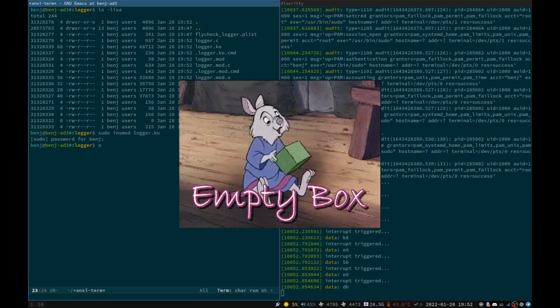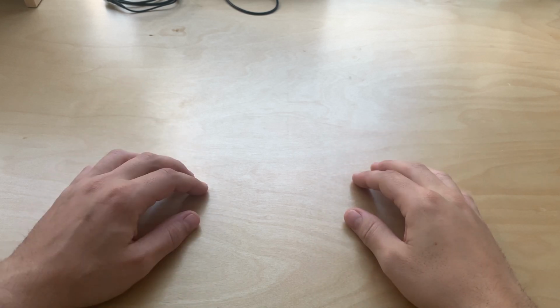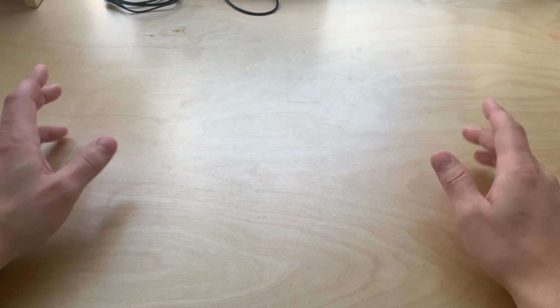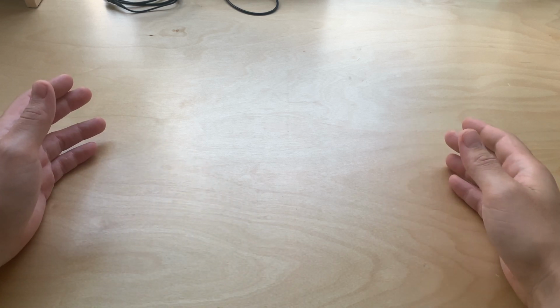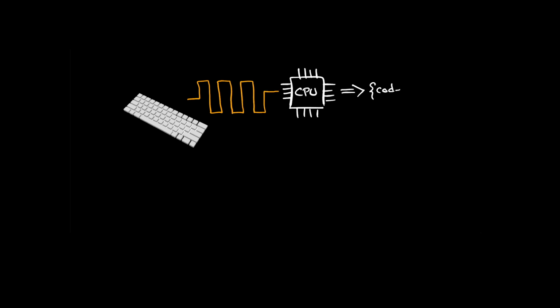And when we press the function key, again, nothing is happening, which is pretty frustrating, I'm not going to lie. Remember, we're only listening for the interrupt signals produced by the keyboard in this particular case. This means we're literally watching for a change in voltage corresponding to a keyboard press event, and then immediately dumping the information we receive to the ring buffer. So if we don't see anything, this must mean the keyboard isn't even sending the information to our CPU.